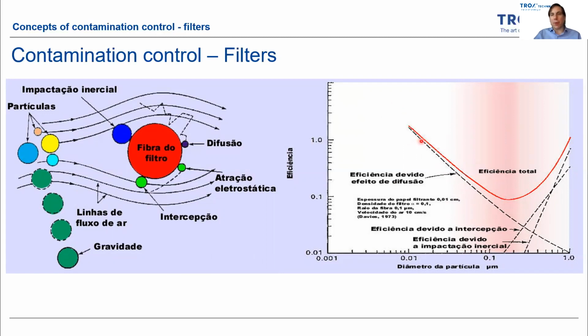And that's quite important. So HVAC filters, and mainly the HEPA and ULPA filters and the high class MERV filters, or the old F9 from the European standards, have an efficiency that increases for smaller particles, and we can see that. And we will see that in some pictures from reports and from the standards itself.